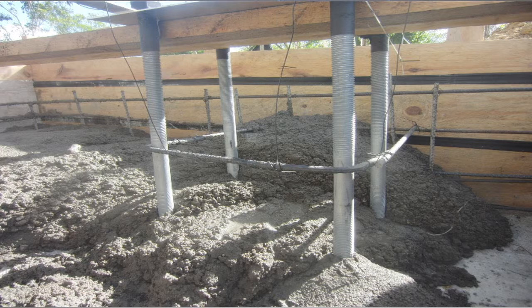It's nice to have this steel in here so that if the cone of failure coming up from the base of the anchor bolts starts to crack, you've got this steel here to stop it. So we added that with the blessing of the designer. We talked to Carter, the fellow back at Barge Wagner, about it. And then this is after it's in place.